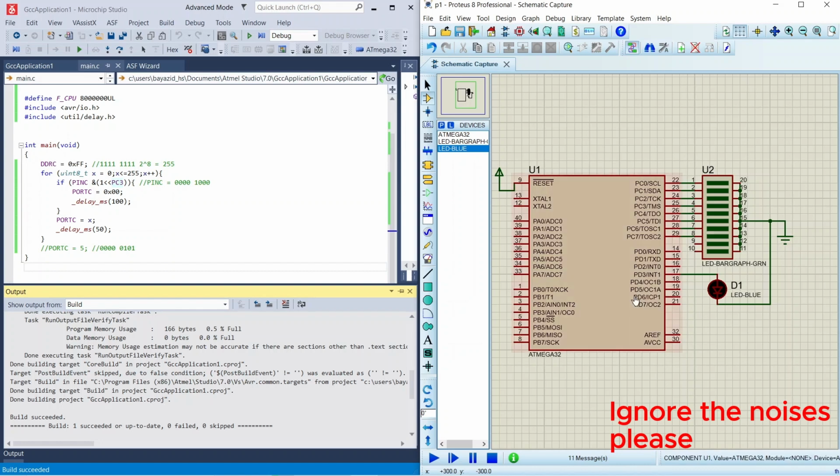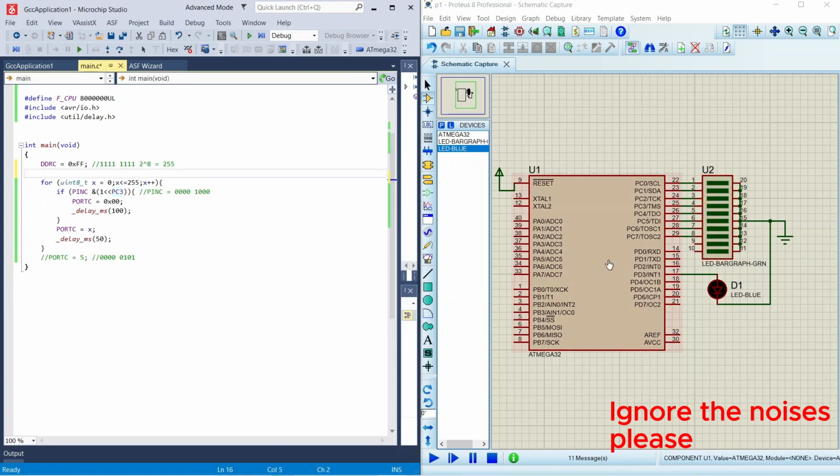Now let's try to use PD3, and it will turn on whenever this will be off. To do that I'll need to add port D as output, DDRD. Let's say only PD3 will be on. So 0b00001000, PD3 means port pin.